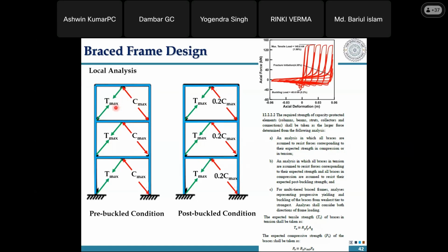You are giving the effect of that lateral force inside, giving this particular look. So if there is lateral force, there is some response or forces that are developed in the members. What you are doing is removing that external force, and internally you are bringing a reaction in the brace systems.